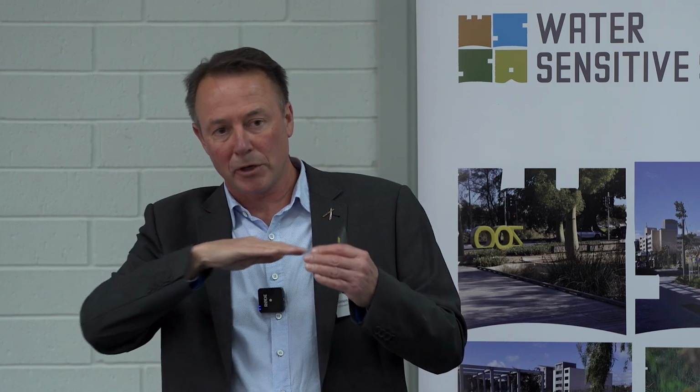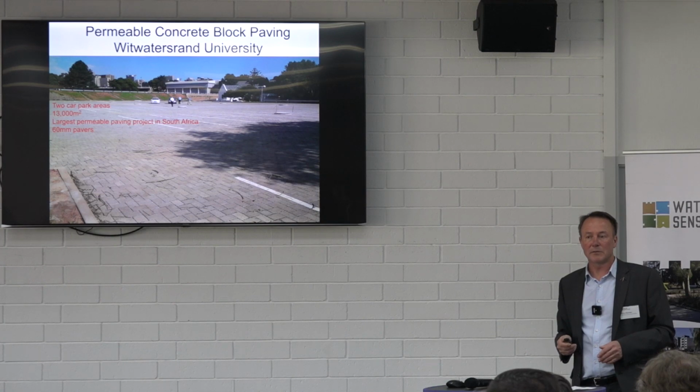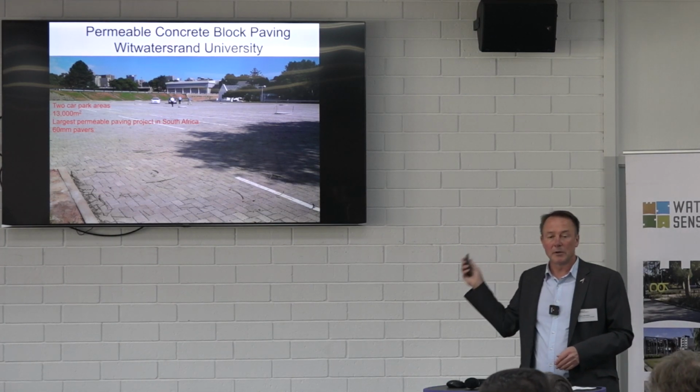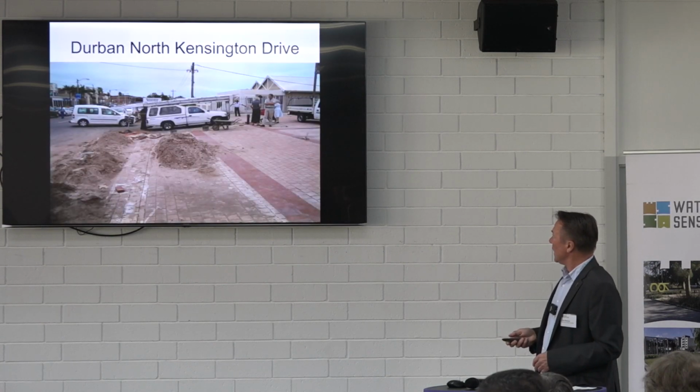If it clogs, what will happen is you'll get a wetting front and a ponding, especially a flat one like that, and it will just aquaplane over to where it's not clogged, and it will just keep doing that until it finds a way out. So that will last forever, but it's hugely over-designed. It wasn't designed with software. They didn't have software at the time, so it's lessons to be learned.